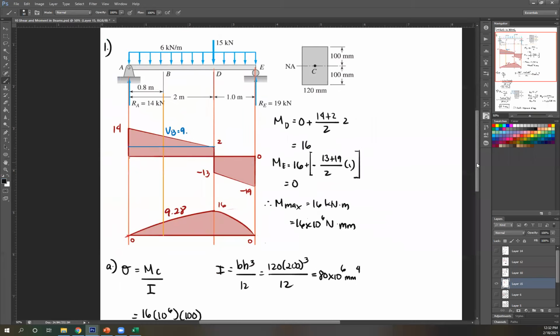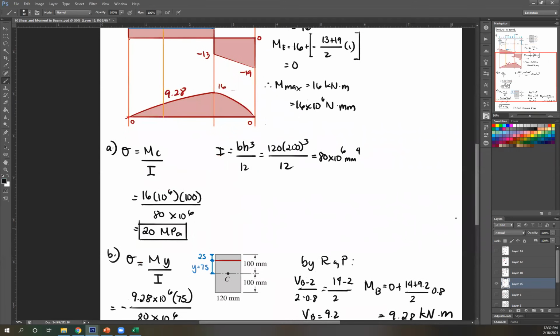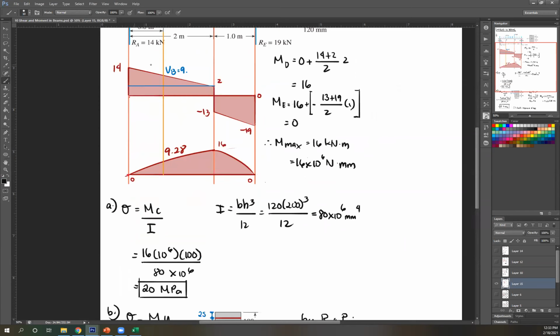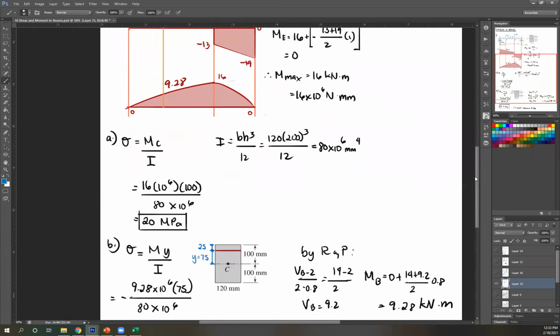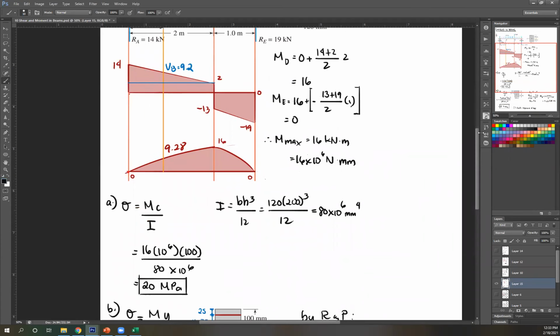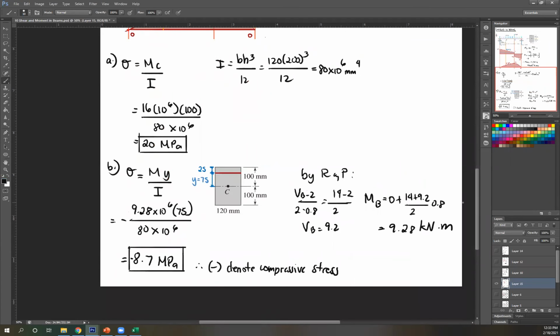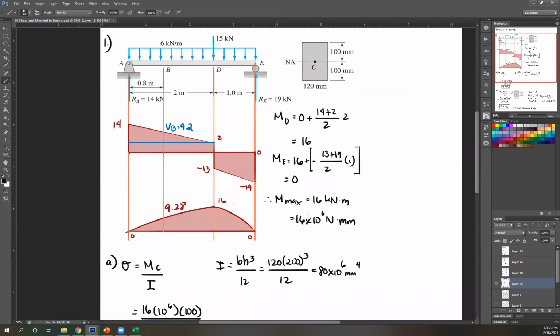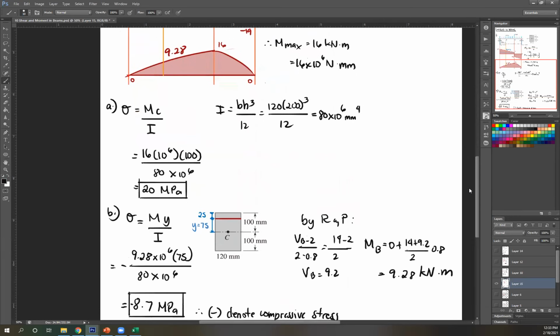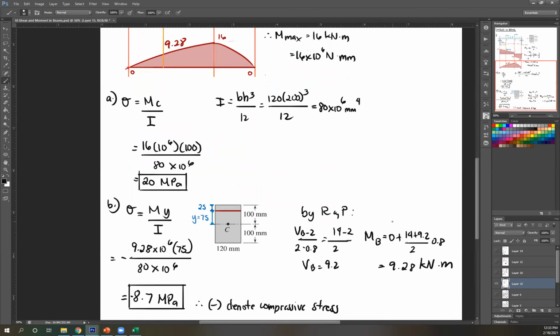So getting the area of a trapezoid again, base 1 plus base 2. So base 1, 14, base 2, 9.2, over 2 times total length. Okay, this length is given to be 0.8. So that's why it's times 0.8. Solving for that, you get 9.28. And that's why I've written 9.28 here, because that's this value. All right? So now that's your n.